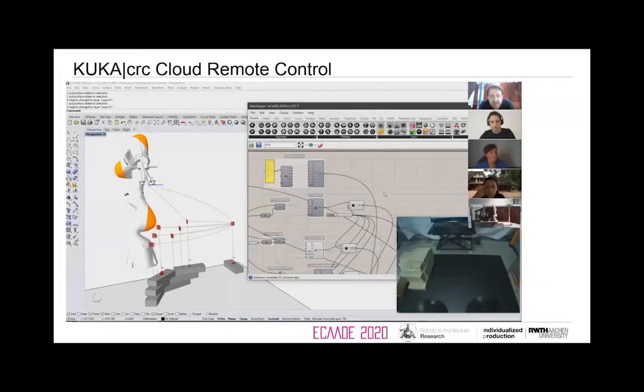In this case, we're using a KUKA iiwa, a force torque sensitive robot. So they learned all about how to use traditional programming tasks like line-to-line movements, point-to-point movements, but also how to use some of the unique features of a force torque sensitive robot, like move until contact. And these are things that are made possible through Dr. Stumm's PhD, where he's allowing us to access the torque sensor, the torque values from the robot and take action on them.